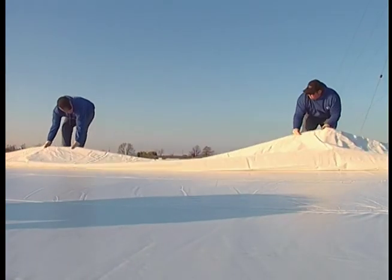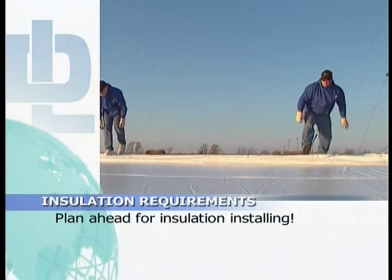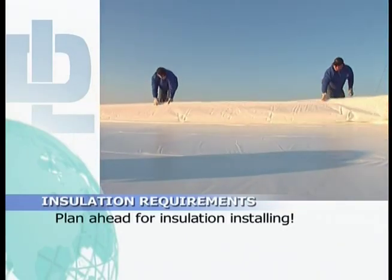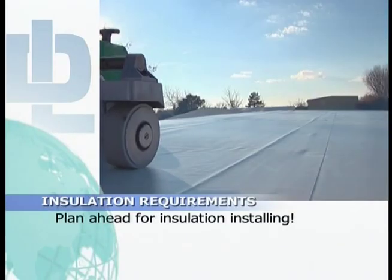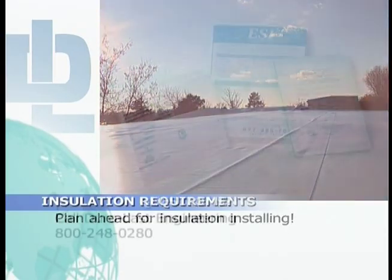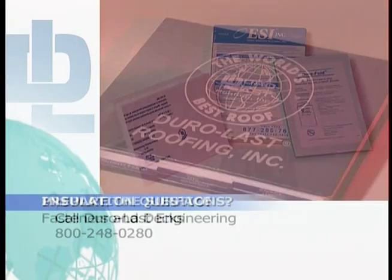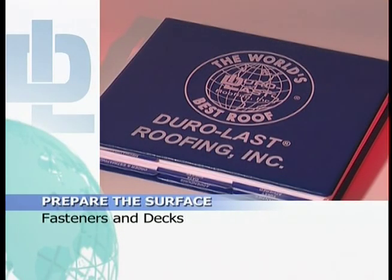This next point is extremely important to prevent weather from ruining your insulation. On any day, install only the amount of insulation that you can cover with Duro-Last membrane and complete before the end of the workday. Always read and follow the insulation manufacturer's fastening specifications. If you have questions, contact Duro-Last Engineering at 800-248-0280. Now, let's see how to correctly use various fasteners in different kinds of decks.